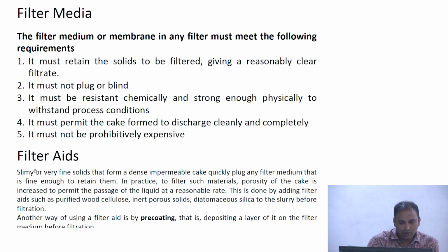The other definition that I want to touch upon is what are called filter aids. As the name itself says, this is something that helps in the filtration process. Typically, if the solid particles in the slurry that you are trying to filter are too small, or are what are called slimy or sticky, then during the course of filtration, the cake that is formed on the filter medium becomes very dense.